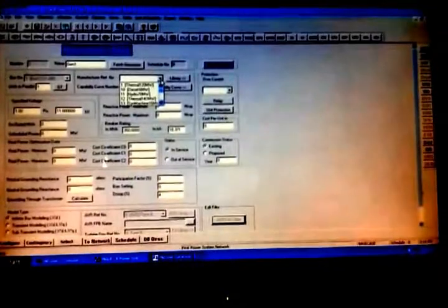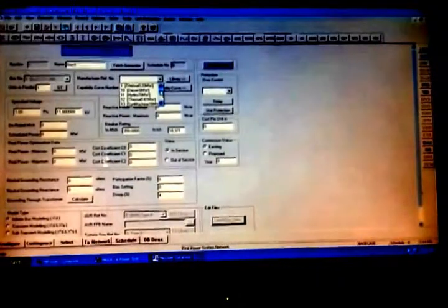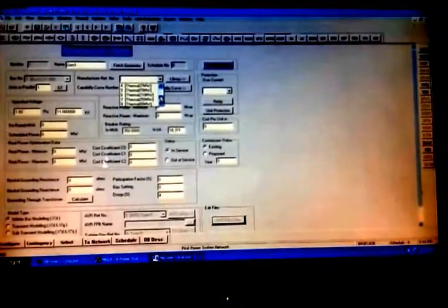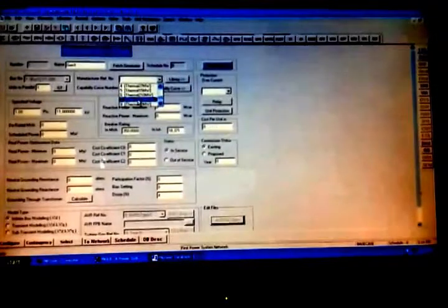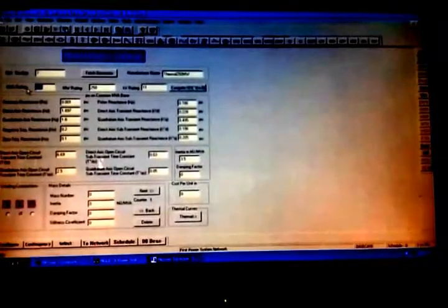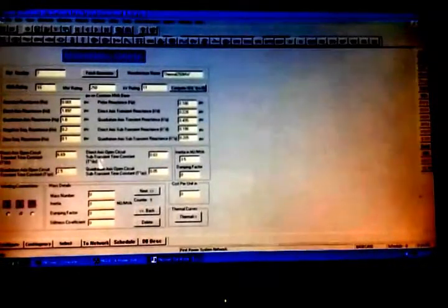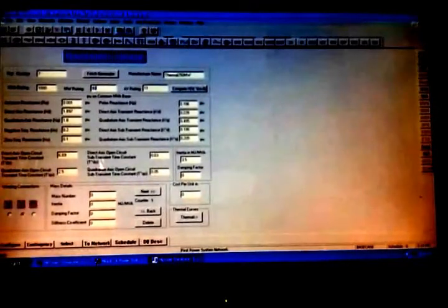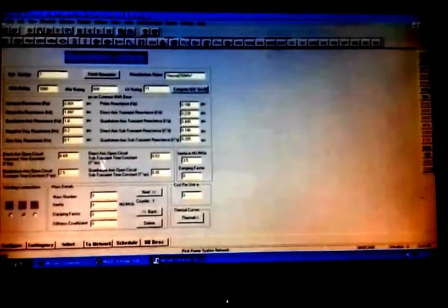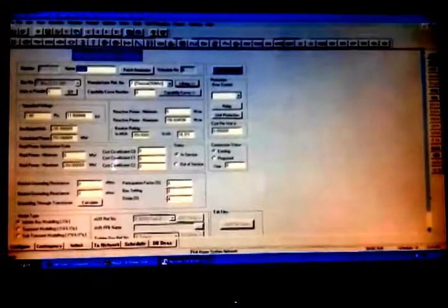In choosing a manufacturer reference number, you have to choose a higher rating than the other generator. So it is a 200 megawatt generator. So here you have to choose a slack bus generator which is more than 200 megawatts. Say I choose it as 250 megawatts. Go to library and then see the required MVA rating is 1000. The calculated value is 800 megawatt. Then save it. Then again close it.